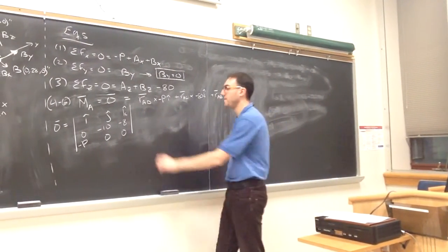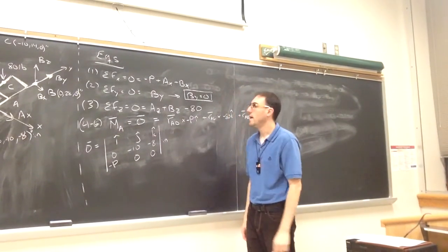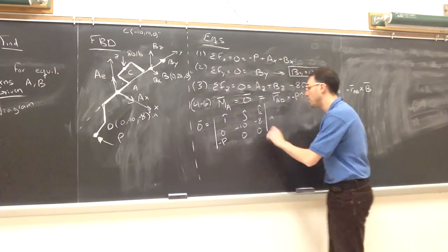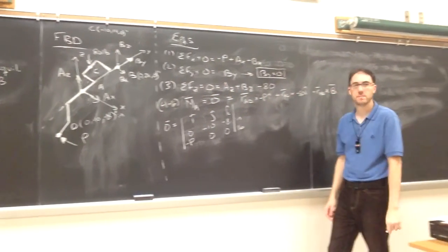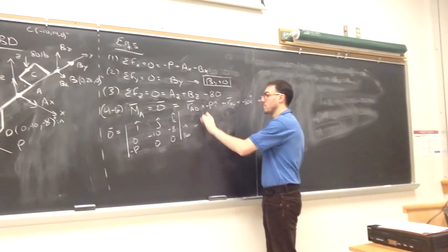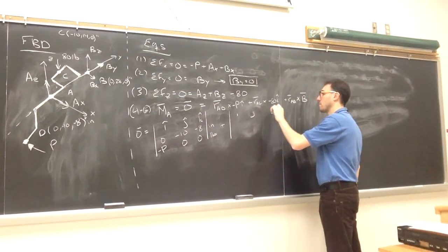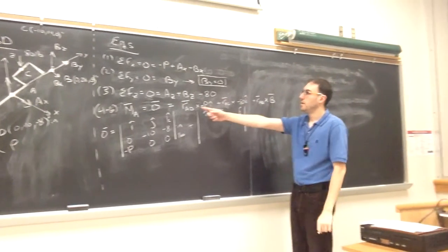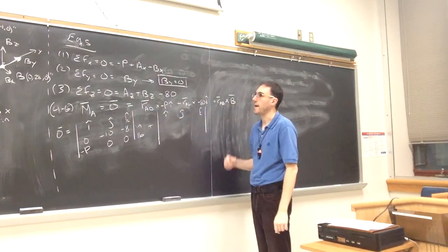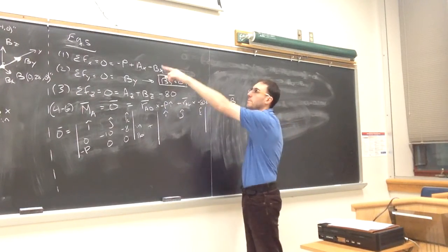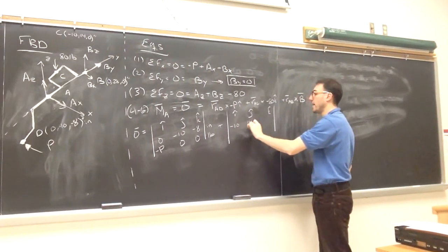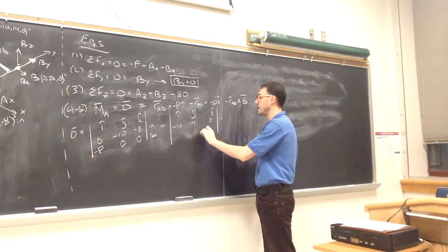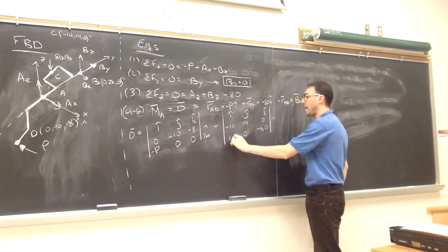The position vector is being measured in inches, and my applied force is in pounds. The first cross product is taken care of, RAC. Coordinates of C up top are negative 10, 14, and 0 inches, and that applied force is in the negative K direction, 80 pounds.